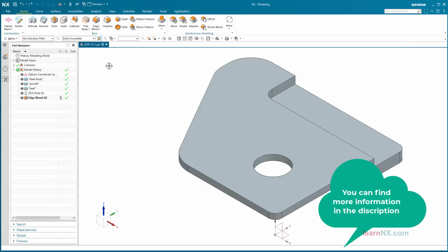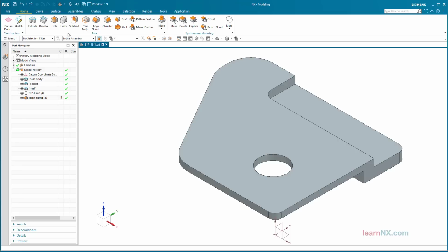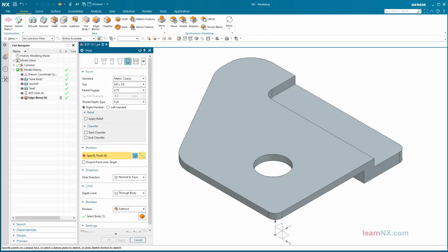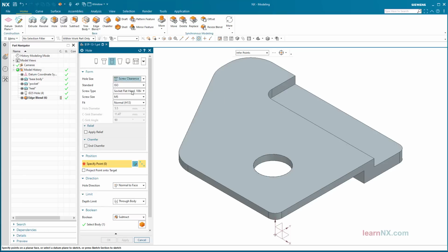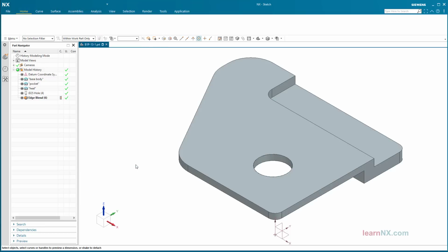Create hole. First, create the circular pattern, with the first hole at 45 degrees. Start the hole command. Select the settings shown and start the sketcher by clicking on Sketch section.